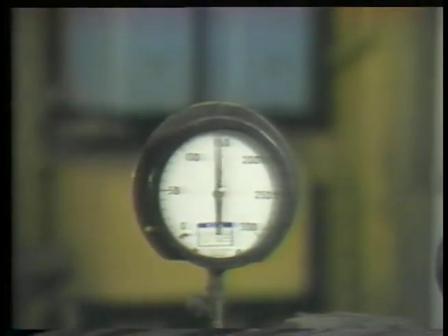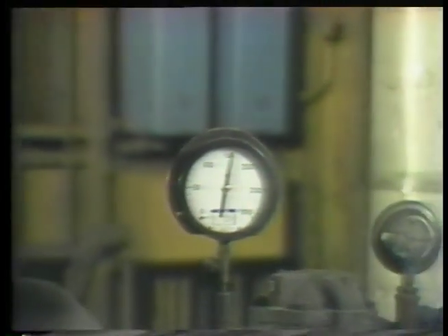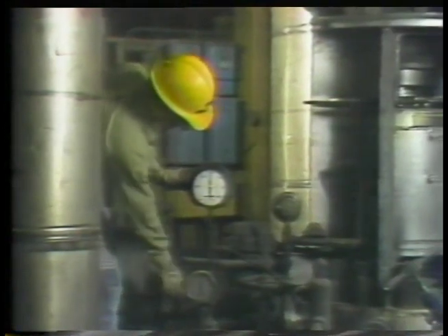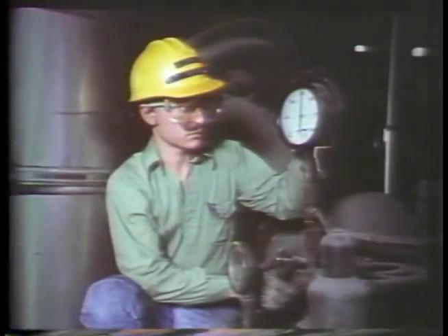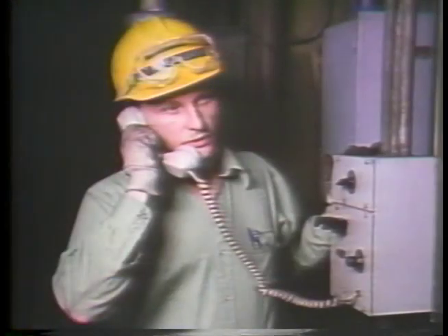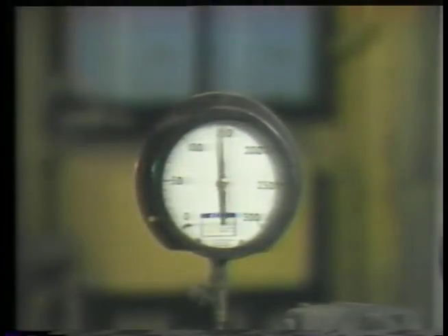A third situation that you may find in the plant is a chattering gauge. Just like a gauge that is forced off scale, a chattering gauge can damage the internal parts and provide you with inaccurate readings. If the chattering is caused by undesirable fluctuations in the signal to the gauge, it can usually be controlled by adjusting or throttling the supply line until the chattering stops. If this doesn't work, then you better call the instrument department so they can find out the problem and correct it. Until this is done, you should suspect the accuracy of any reading taken from this gauge.